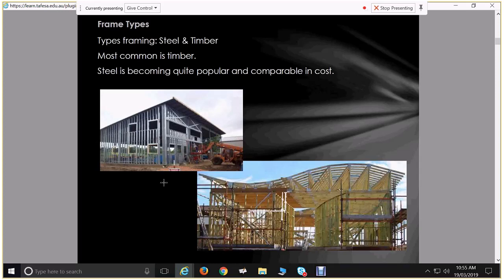Does that have anything to do with taking up earthquake vibrations or cyclonic zone areas? There we have to use steel framing stuff. Certainly in South Australia, we don't consider those things. So we're not in a cyclonic area. So that's not a thing which is factored in. We're also in a very stable part of the world. Yes, we do have seismic activity happening here in Adelaide, but it is very small. It has been very small to date. There's nobody saying we have to design for earthquake loads.